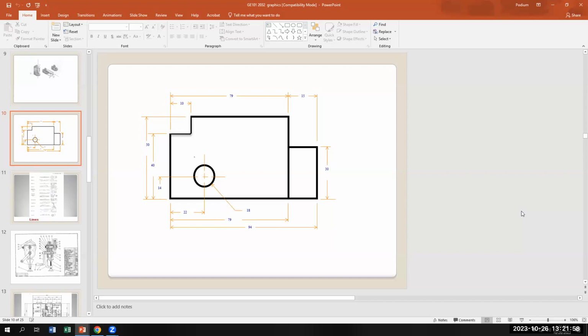Your goal with dimensioning is full shape description. So you want to try to capture the whole shape, so that when you hand it to somebody else, they can actually make it. And also full position of everything. So if there's a hole, you should have a position. All right, good. Give it a try.